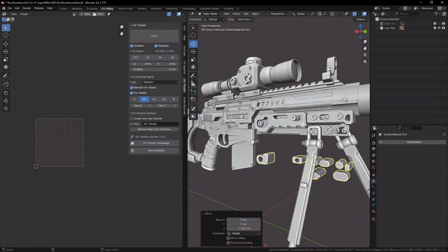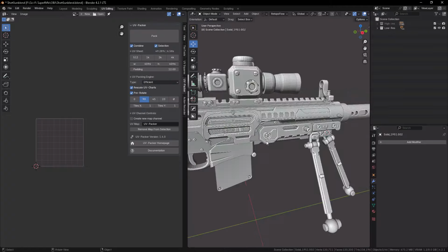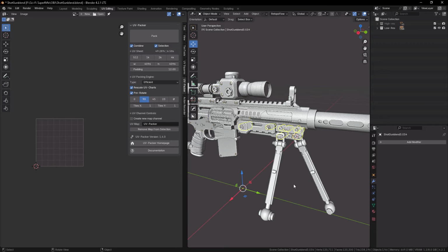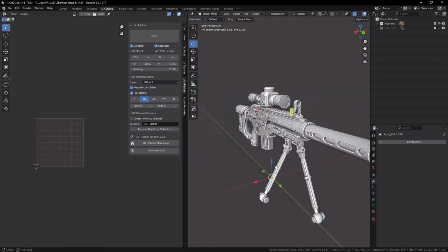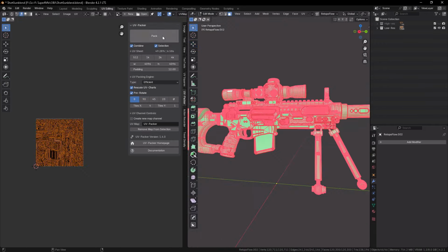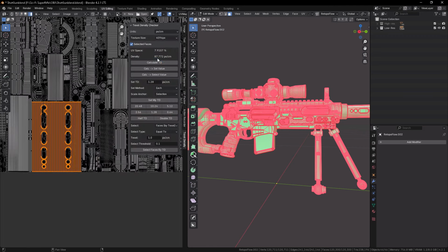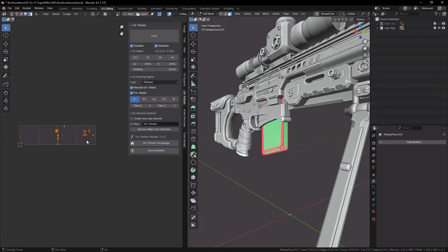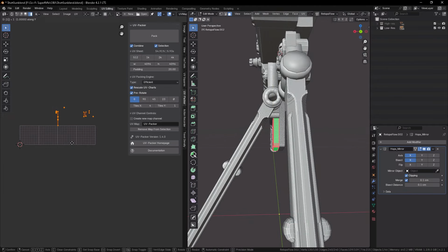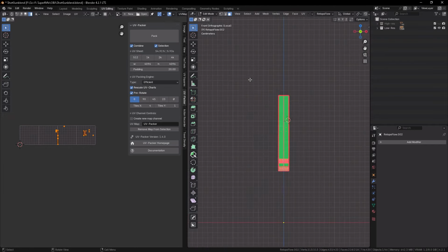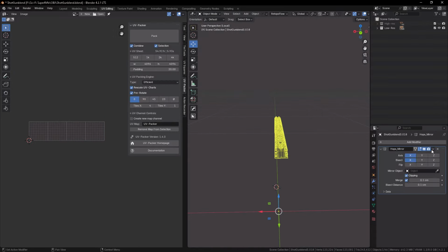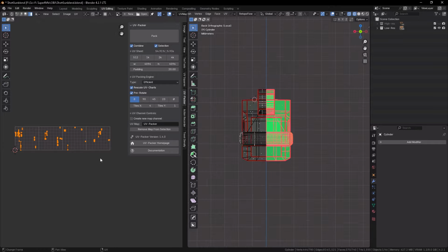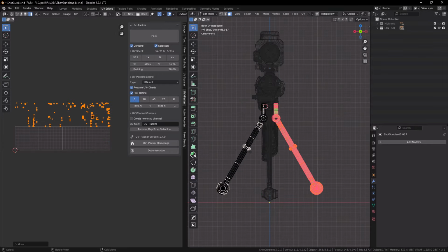This way, they will occupy the same UV space but will be offset by 1 unit. This technique allows us to maximize our UV space during the packing phase, and by shifting them over, just like in the video, we can eliminate overlapping UV islands. Isn't that fantastic? So that's the essence of the mirroring concept, folks.